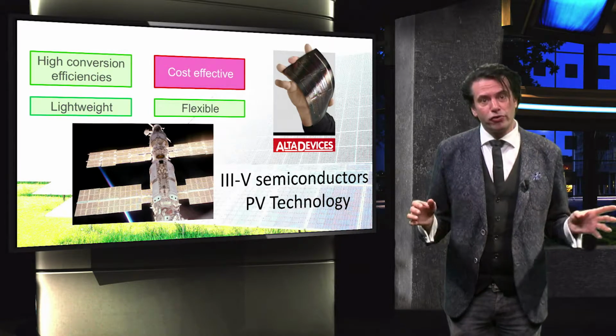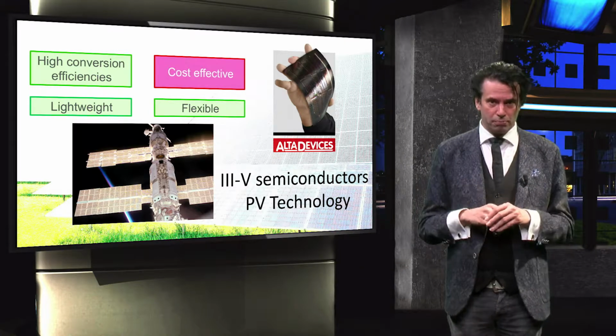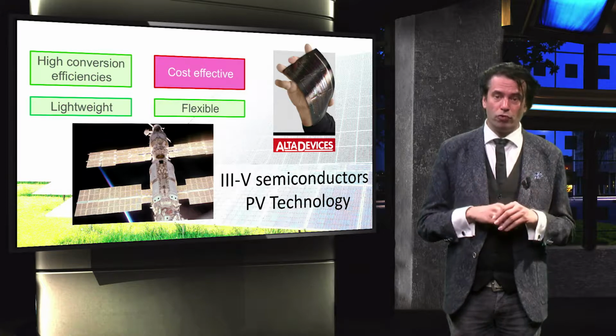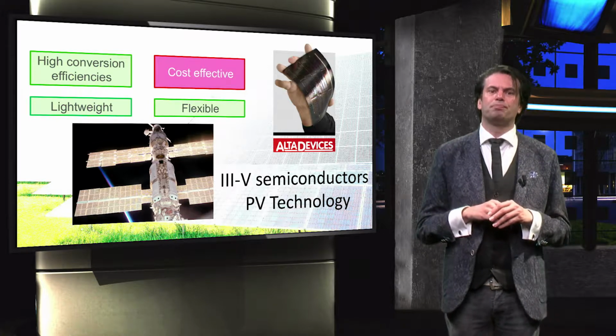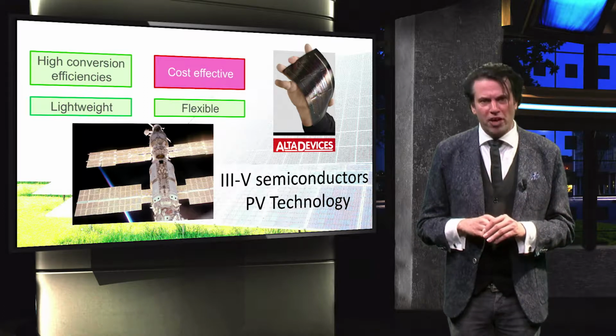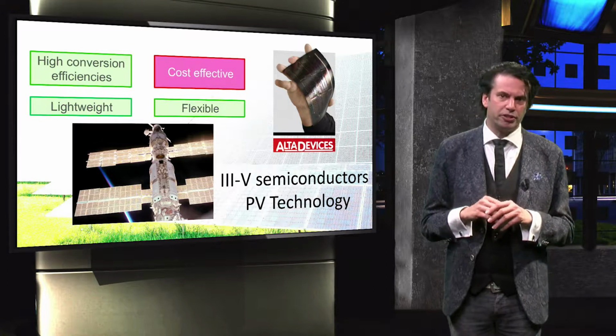For concentration photovoltaics, high efficiency per small area is the most important design metric. Therefore, III-V PV technology is the most suitable for concentration approaches. The challenge for the III-V PV technology is the cost price per watt peak due to expensive processing technology and resource materials.